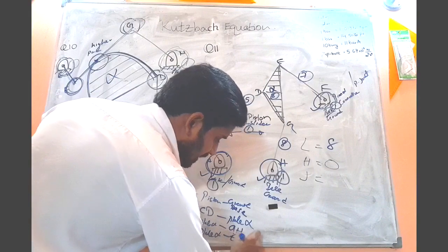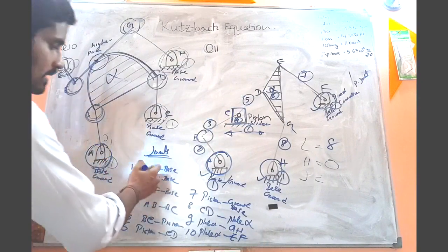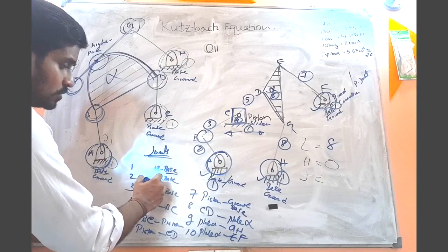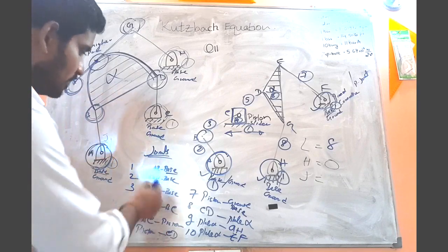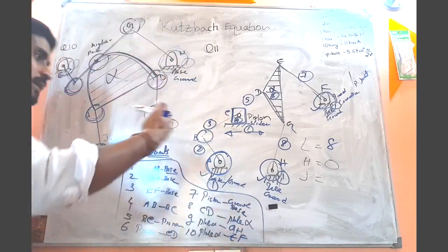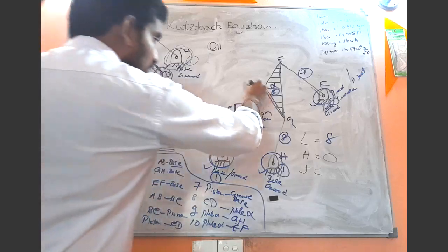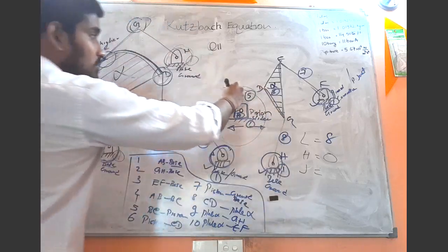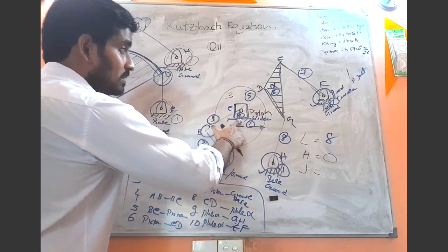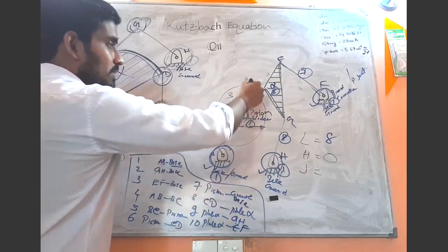So it is better if you can write like that. What is joint number 1? Link AB to base. Second one, link GH to base, right? Better if you can write like that, because you are still at the initial stage of studying these fundamentals. Now see, this one is a very special case because there are 3 joints. One joint connects BC to the piston, then the piston to CD, then the piston to base, right? Very special case.